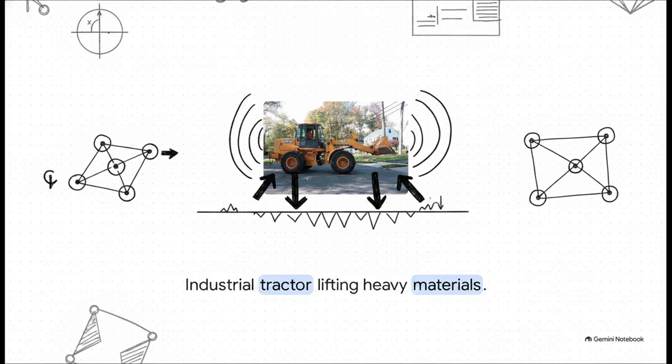When this tractor lifts a heavy bucket of earth, those forces don't just magically disappear, right? They transfer directly through the frame, dynamically shifting some really intense physical loads across the front and rear axles. As an industry engineer, you need the spatial awareness to calculate the exact ground reactions at those tires so the axle doesn't literally snap under the pressure.